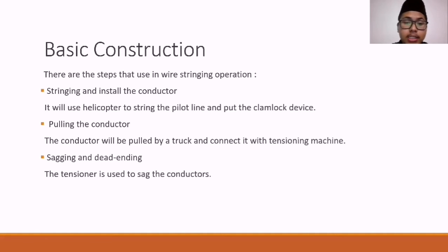After the conductor is pulled, it needs to sag because conductors can expand and contract according to changes in weather or temperature. For example, when they are exposed to high temperature, they will become too tense and may be damaged.